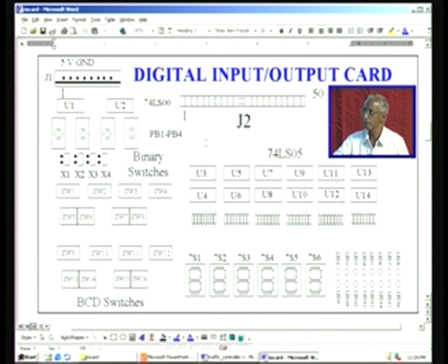In addition to this, we also have connected to the very same pins these 7 segment LEDs. In fact, if you notice, there are 6 7 segment LEDs. What is not shown in this figure is a decimal point, but we will be seeing that separately when we have a zoomed version later on. And that would mean 7 segments plus 1 for decimal point would take you 8 bits, and once again this is connected from pin number 3, as in the case of the push button switch or SW1 or SW5, and the order in which this is connected is A, B, C, D, E, F, G, and then decimal point, in that order starting from the left.